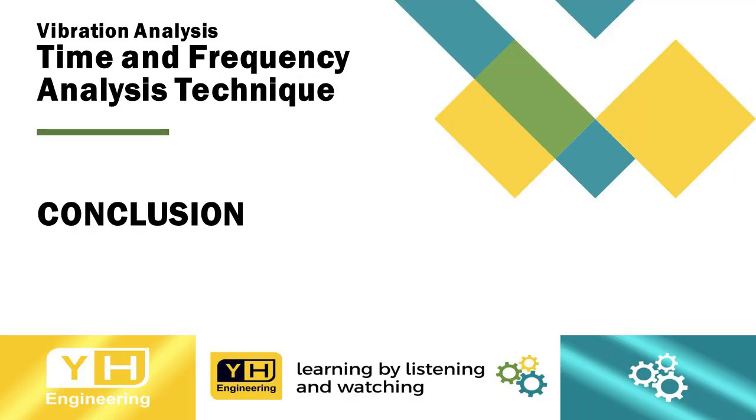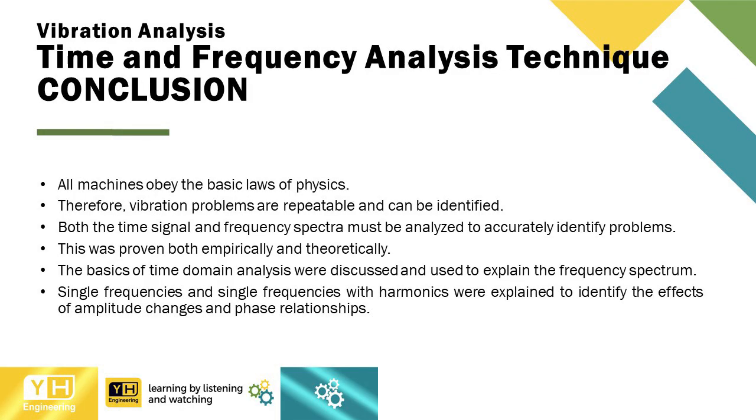Vibration analysis. Time and frequency analysis technique. Conclusion. All machines obey the basic laws of physics. Therefore, vibration problems are repeatable and can be identified. Both the time signal and frequency spectra must be analyzed to accurately identify problems. This was proven both empirically and theoretically. The basics of time domain analysis were discussed and used to explain the frequency spectrum. Single frequencies and single frequencies with harmonics were explained to identify the effects of amplitude changes in phase relationships.